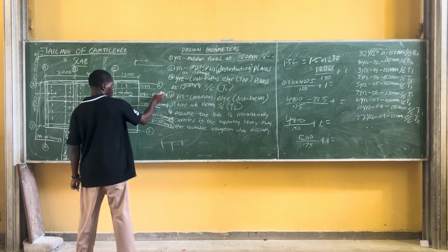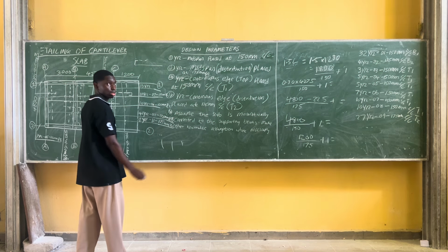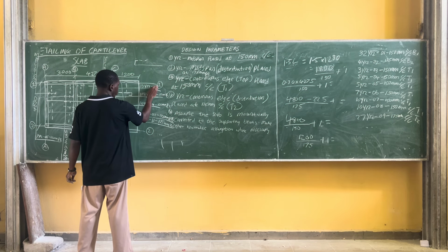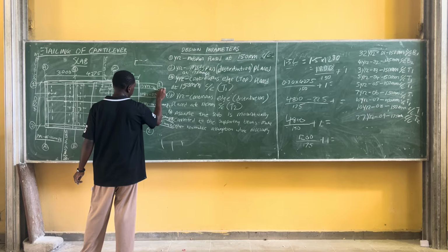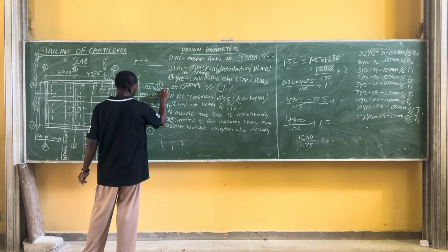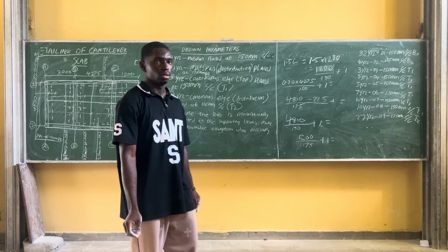C11. This side, bar mark 12, at 150 mm center to center, T1. We are done.